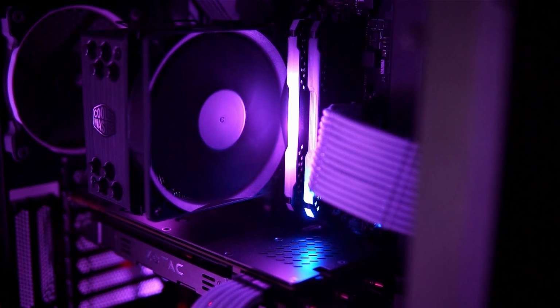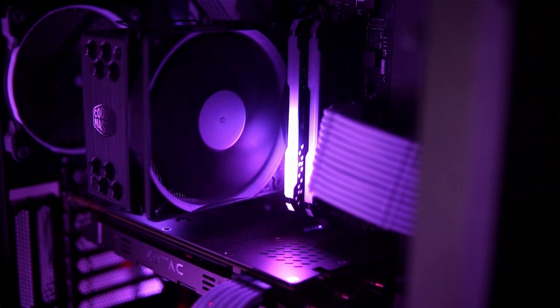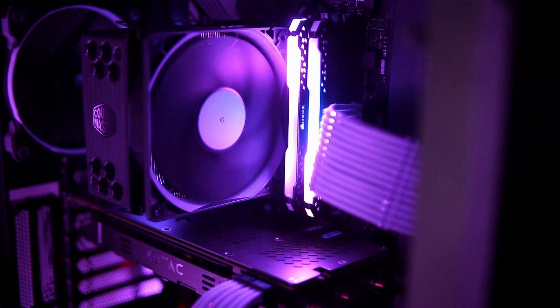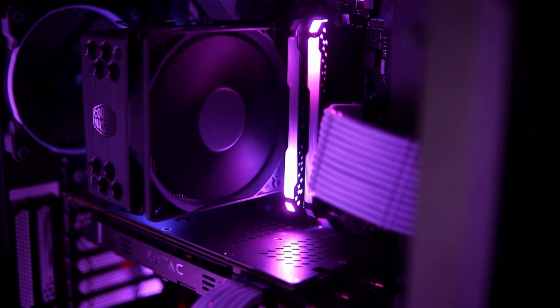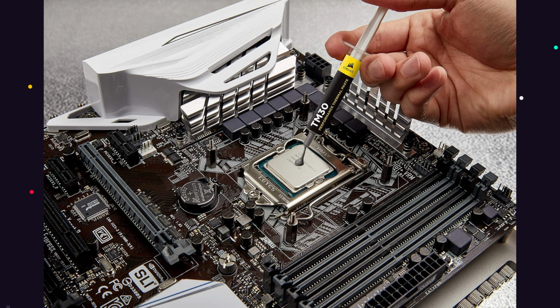So alright, let's talk about how to install your CPU cooler. It might seem intimidating, but with the right steps, it's a breeze. Here are some tips to make the process smooth and effective. First off, apply your thermal paste correctly. Use a pea-sized amount of thermal paste on the CPU before attaching the cooler.